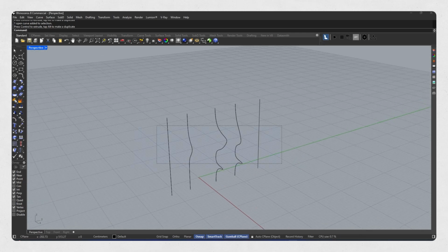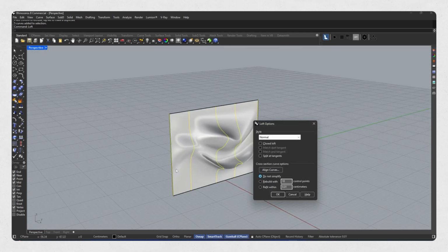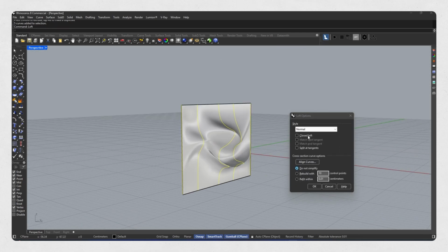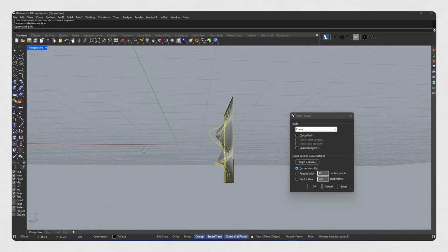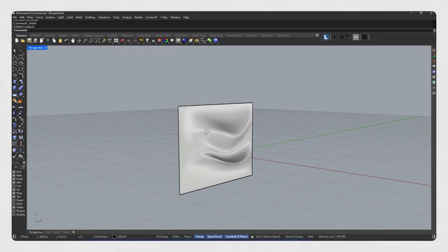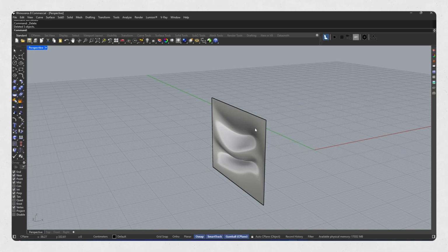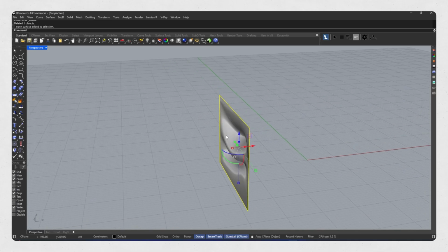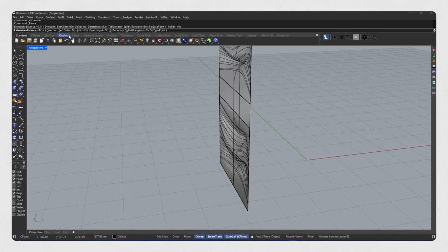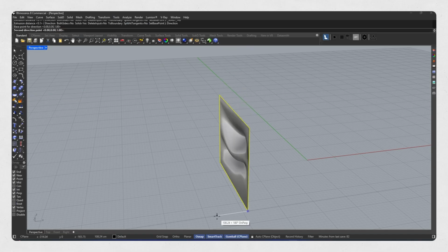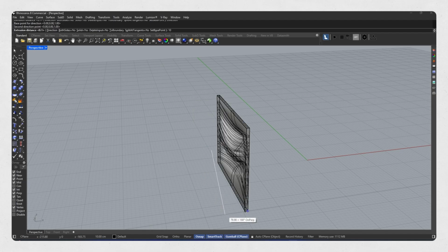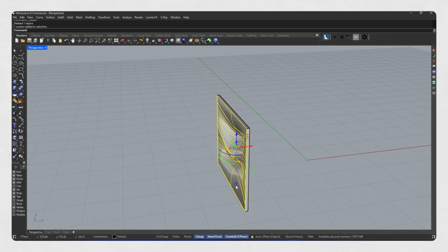It's just that easy. We've already made it through a major part of the modeling process and built the main surface. Now, let's dive into the whole cutting and contouring thing. Before we contour, just to get a cleaner result, I'm going to use the extrude surface command to give the surface some thickness. Then, holding down Ctrl plus Shift, I select the back surface and use Set XYZ Coordinates to flatten it out so it aligns the way we need it to.